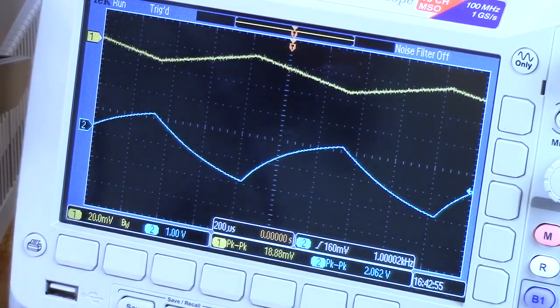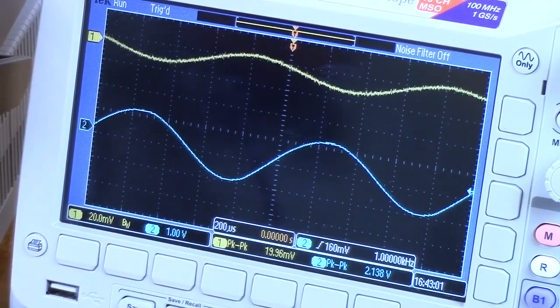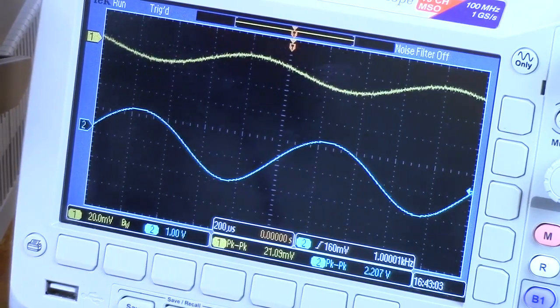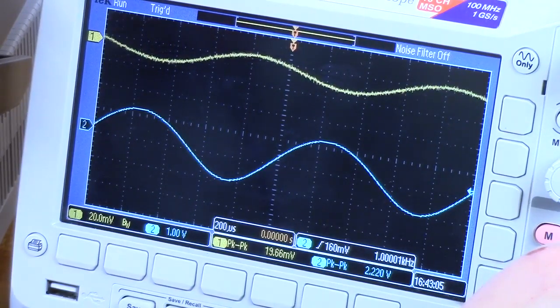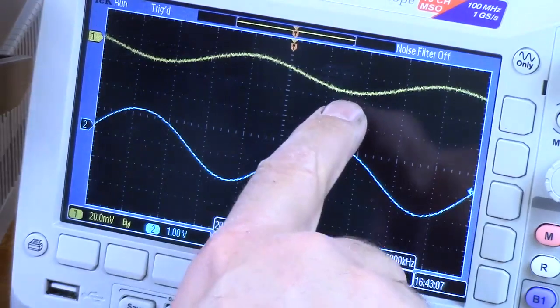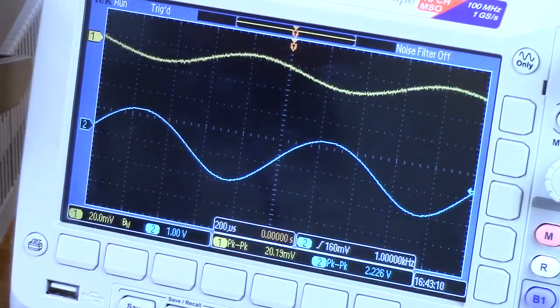But if we would like to measure a gain, let's go back to a sine wave, waveforms, and the sine, and it'll look a lot better. There is still some distortion, but if we're going to measure the gain, our scope is turned up as high as it can go, 20 millivolts per division.